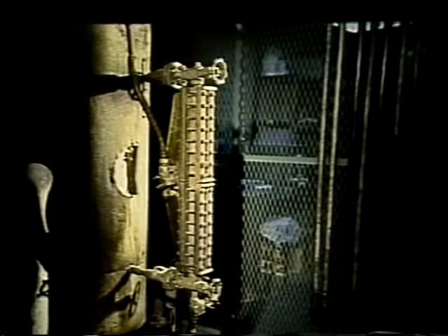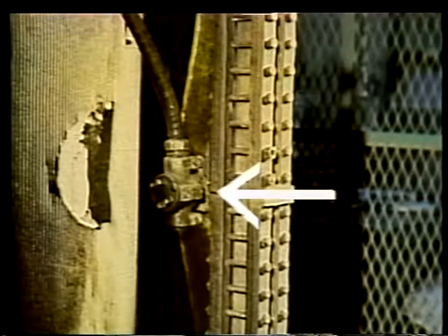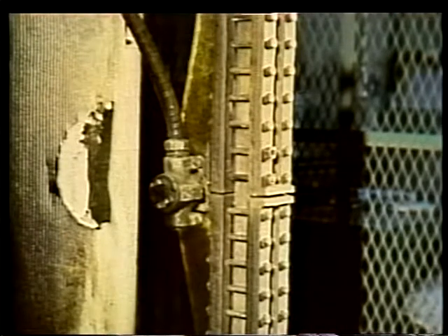If the gauge drains properly, remove the gauge illuminator. Usually, the illuminator is hooked onto the gauge and can be lifted up and pulled off. If the illuminator is dirty, clean it and then set it down where it won't be damaged.